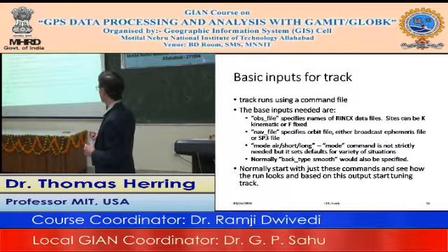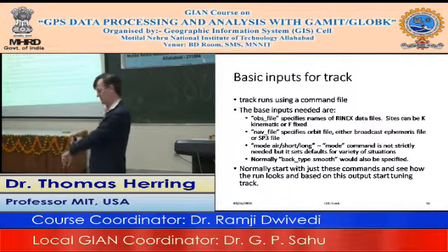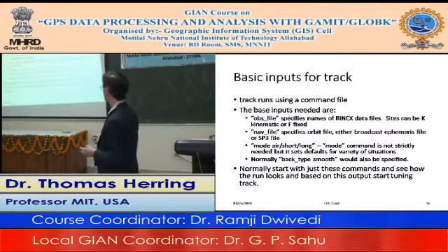Then you have to give it a nav file, which is either an SP3 orbit file, if you have it available, or a broadcast ephemeris file, if that's all you have. If you're doing any post-processing, we certainly recommend that you get the SP3 files. Then there are 3 modes that it defaults to.